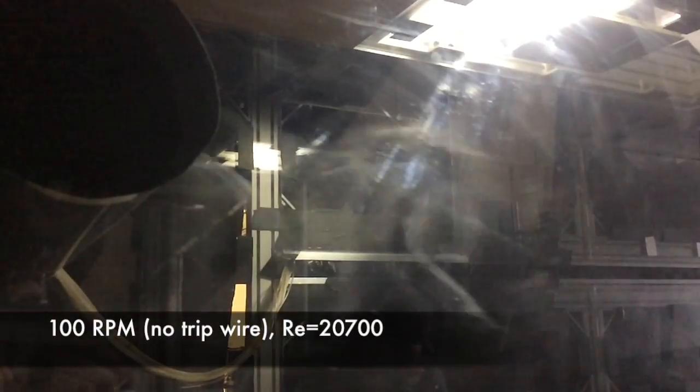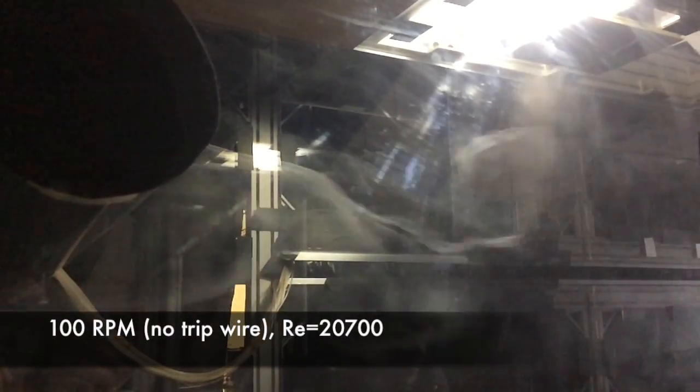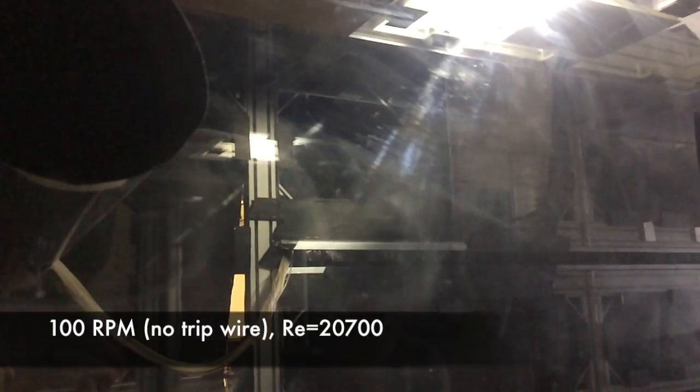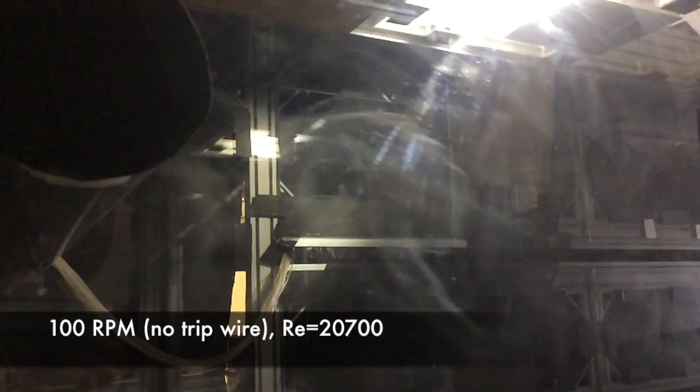Here the phenomenon of vortex shedding and laminar flow can be seen at a Reynolds number of around 20,000. The shedding of these vortices is due to the formation of an adverse pressure gradient along the surface of the cylinder wall, which causes the boundary layer to separate from the surface of the cylinder. This detached flow then accelerates past the cylinder's rear surface, causing a drop in local pressure. This local pressure area then accelerates the flow from the other side of the cylinder, which forms another adverse pressure gradient and repeats the cycle on the other side of the cylinder.